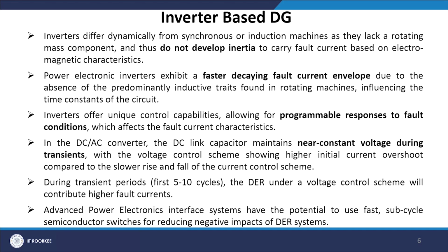Power electronics inverters exhibit a faster decaying fault current envelope due to the absence of the predominantly inductive traits found in rotating machines, influencing the constants of the circuits.